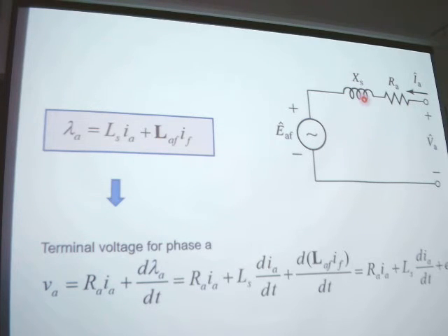The EAF, we can think it is the back EMF. It's for the stator, but it's influenced by the rotor. For a synchronous machine, we use the stator circuit. It's enough. The influence is included in the EAF.